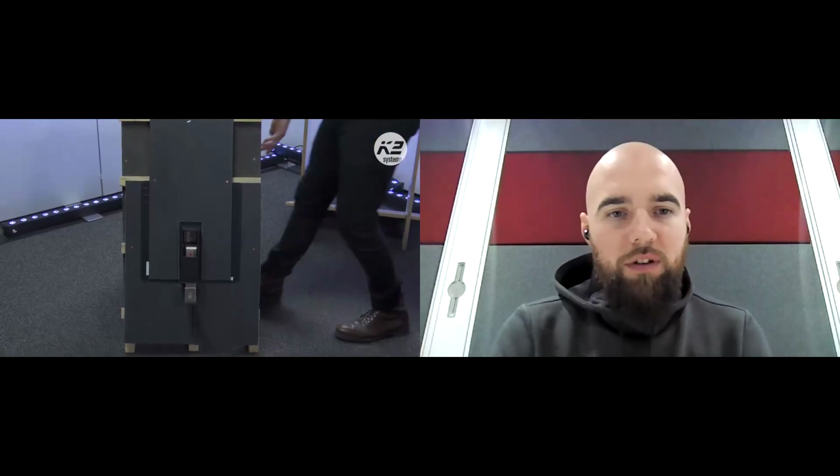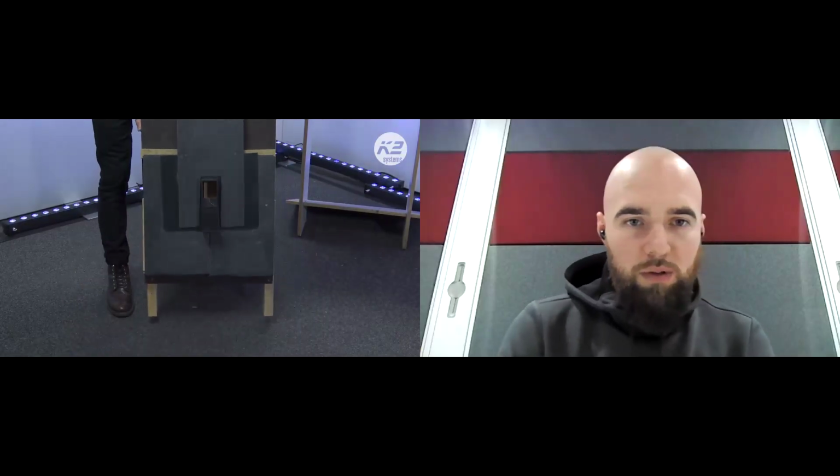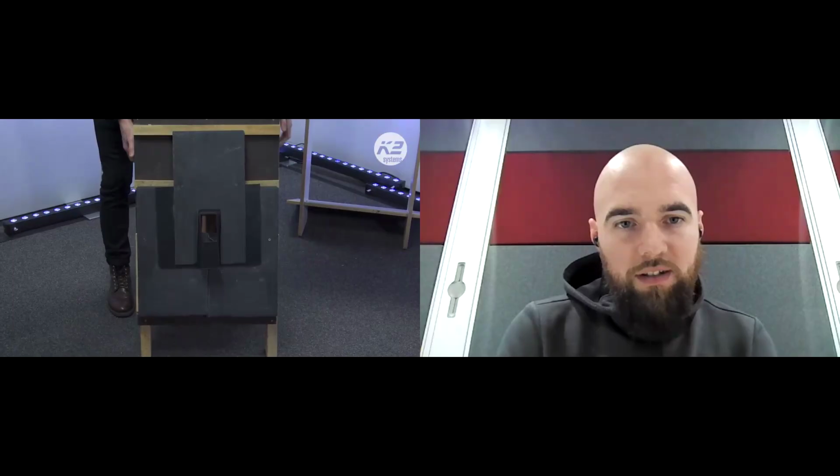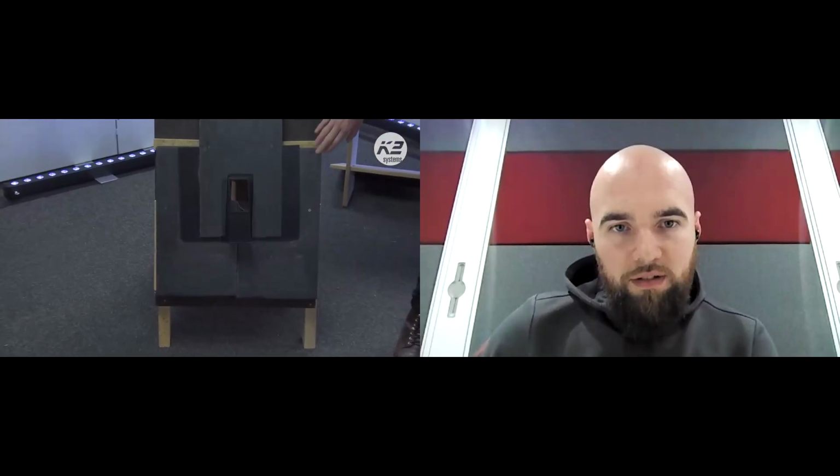And then I think on the other side, is it the same hook on the other side, just the old flashing? So I don't think we have a hook on this side, but we just have a different setup with the slate that needs to be cut. So maybe you could briefly talk about that, because in this one, I think we've also cut the slate out from the two pieces underneath.